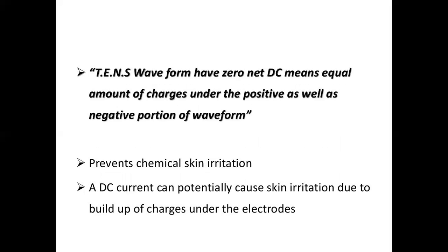TENS waveforms have zero net DC, meaning an equal amount of charge under the positive as well as the negative portion of the waveform. It prevents chemical skin irritation. A DC current can potentially cause skin irritation due to buildup of charges under the electrodes.